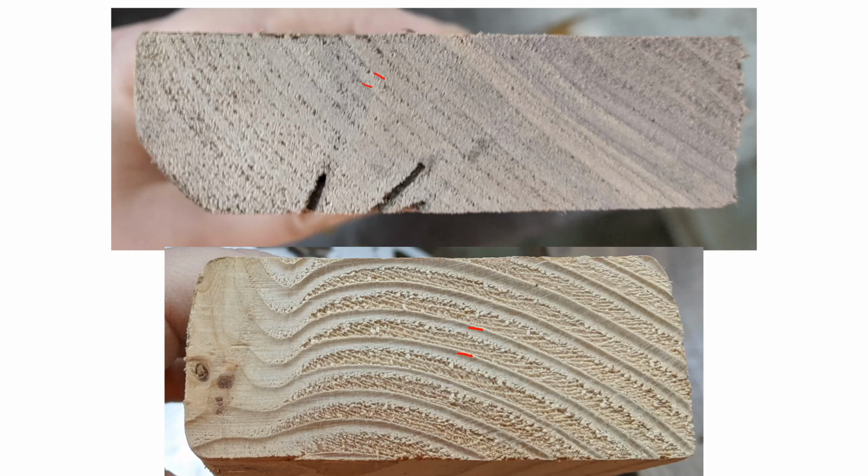And that high cost comes directly from the time it takes for hardwood to grow. If hardwood grew as fast and as rapidly as softwoods, we would probably only use hardwoods for construction. But because they take so long to grow, in most cases we are better off using softwoods in construction, because in construction the primary motivator is cost rather than just strength per unit area.